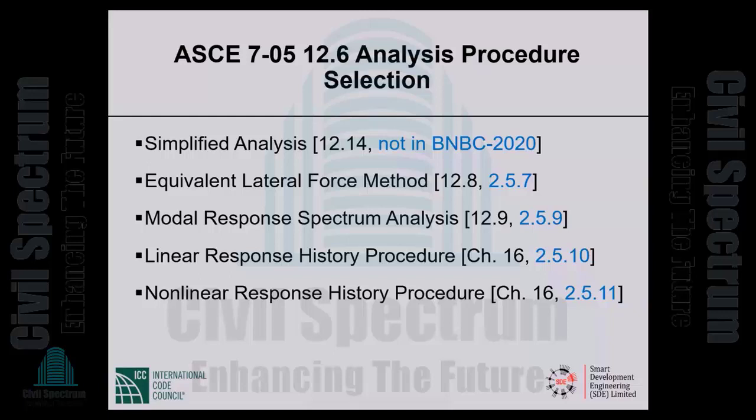Linear response history analysis, chapter 16 of ASCE 7, 2.5.10 of BNBC. Nonlinear response history analysis, chapter 16 and 2.5.11. Equivalent lateral force is a static method. The other three are dynamic analysis methods. Equivalent lateral force procedure is allowed to be used under restrictions. The dynamic analysis methods can be used anytime.